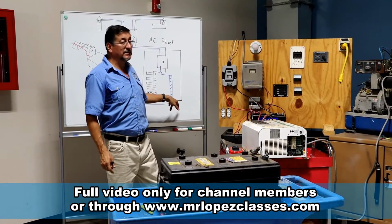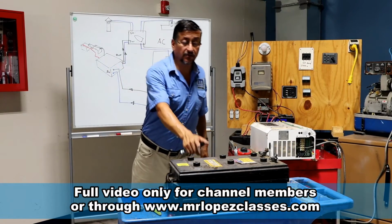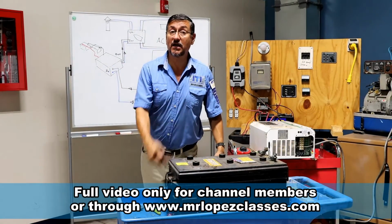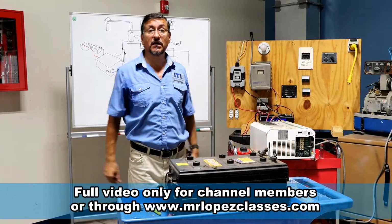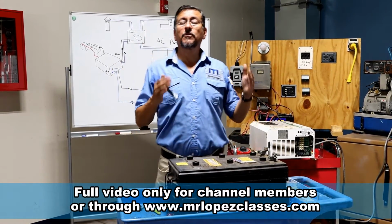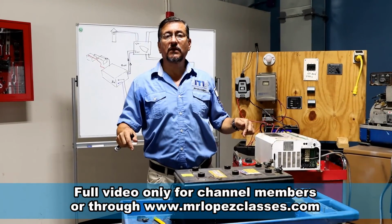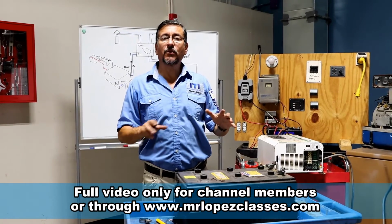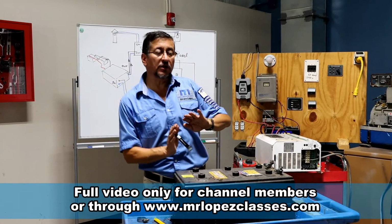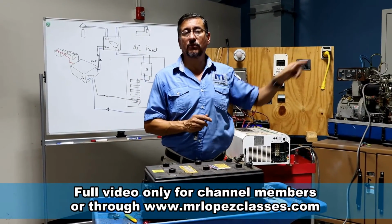In this particular example, I need 1,000 amp-hours. With two batteries of this type, I have 1,600 amp-hours. This is a good selection. The secret is to select the appropriate batteries in order to keep a good group of batteries properly installed, properly organized, in order to supply the amount of AC power required for the customer in the boat.